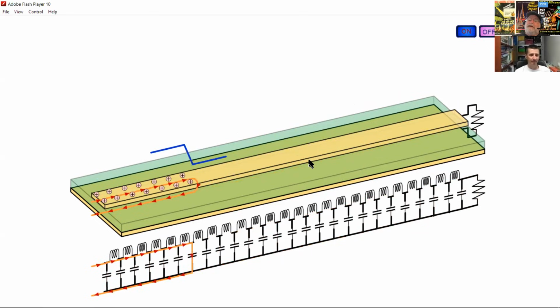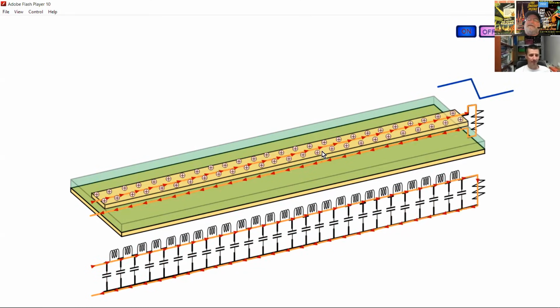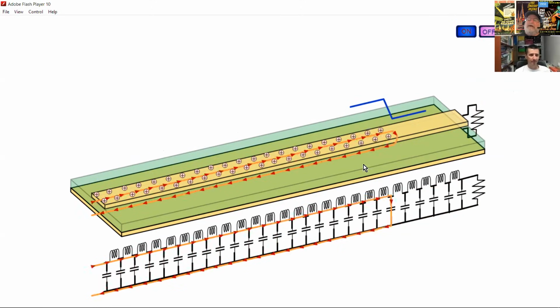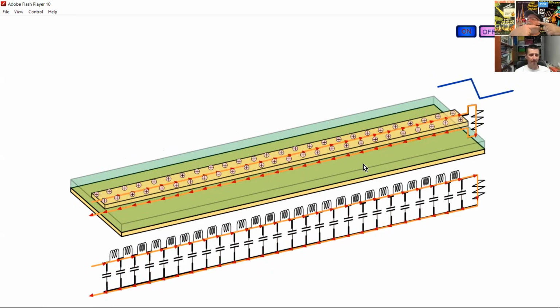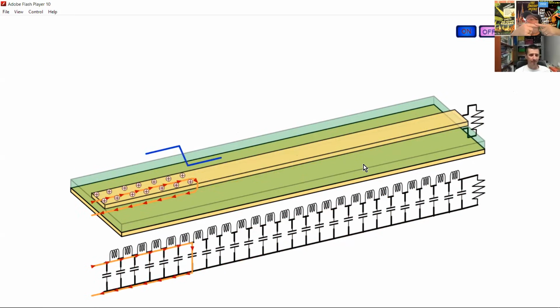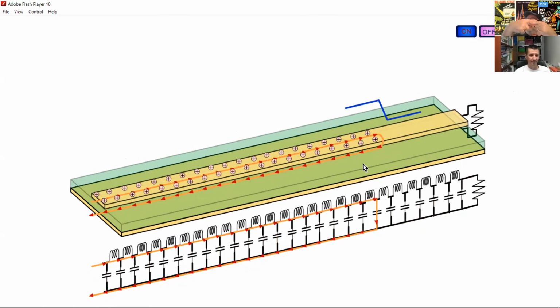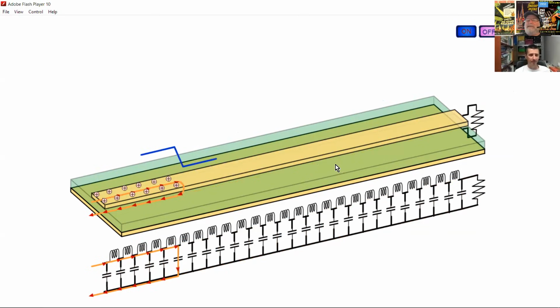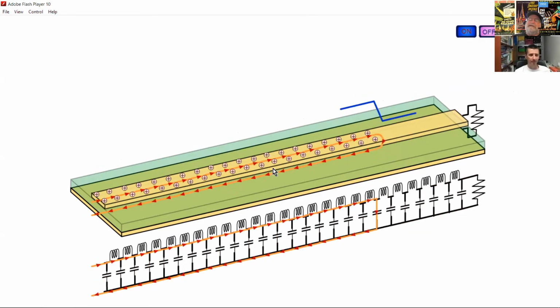And so it's easier to approximate it by saying the current goes around, and in going around, that's a longer path. There's tighter concentration of the current, so there's higher inductance, and so we approximate that gap as an inductive discontinuity in the return path. And if you have a dI/dt through an inductor, what do you get? If you have an inductor and you have a fast changing current through that inductor, you get a voltage drop from one side to the other. And that's what happens in the plane. You get a voltage drop from this side to this side because of that inductive gap.